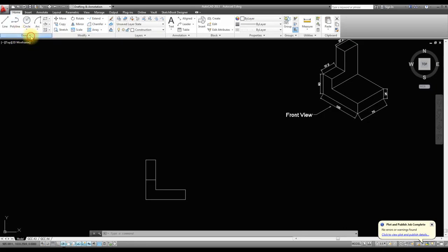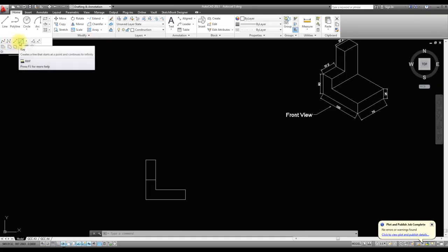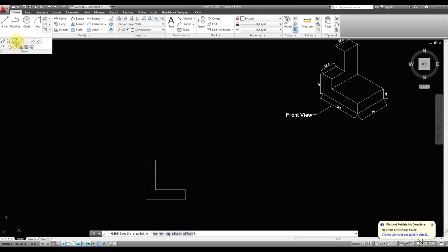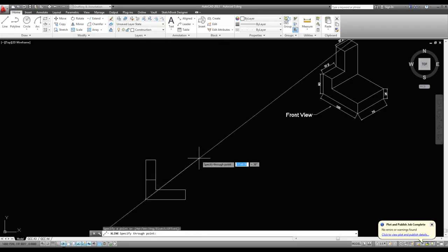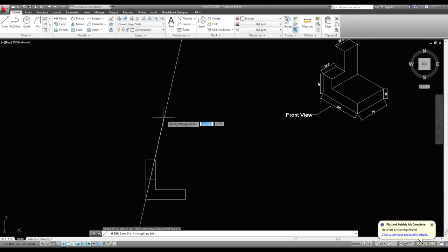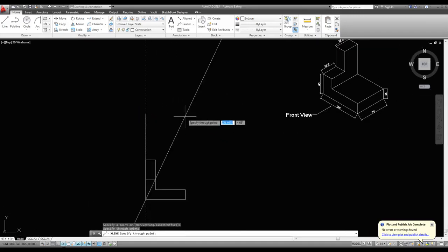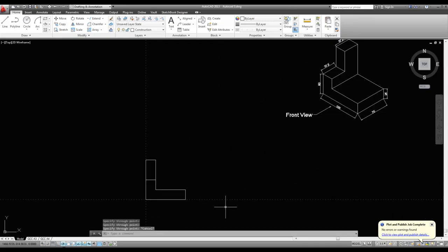But what I've got to do first is the construction lines. I've gone to the construction layer, and I drop down this dial that says draw. These particular lines here are spline fit and spline CV, but this one here is the actual construction line. This one here is a ray, which is a different sort of thing for different drawing. But the construction line, I've got it so that the layer is a dotted line so I can tell the difference. Now you notice how it locks on vertical lines. And a construction line goes infinitely.